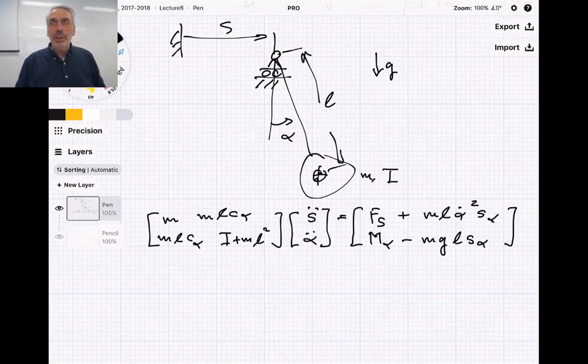to the speeds, and then when you have them, you have to differentiate them to time, but differentiating to time means differentiating to the coordinates, and then the coordinates to speed. So there's a lot of work going on where you say, oh, do I have to do all this work? And the answer is no. The only work you need is Jacobian, convective terms, and you're done.